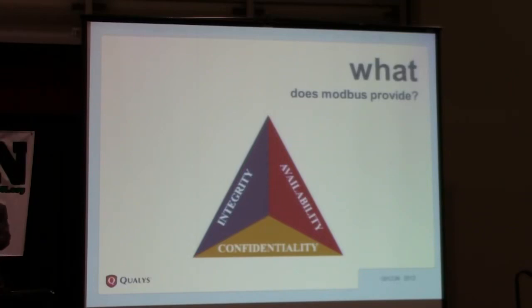So we said, okay, Modbus was a pretty old protocol, as many of you who raised your hands know, maybe 30 years old. And it was not really designed with security in mind. So we created a signature saying that if we find Modbus running in your environment, or your HMI and your field equipment communicates using Modbus, then you have a potential vulnerability, because the protocol itself doesn't support all these things.